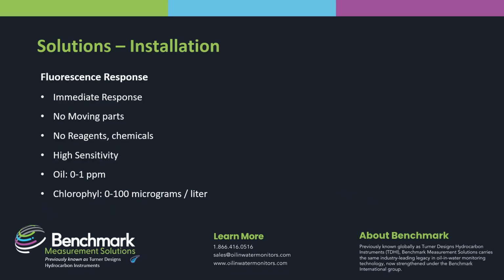Fluorescence is used for this because the measurement has no moving parts, there's no reagents, no chemicals needed. A simple lamp illuminates the process and the presence of either oil, or if the lamp is a different wavelength, algae will be detected by their response. Oil, or hydrocarbons or fuels, depending on how you call them, can be measured significantly below 1 part per million. Most membranes have a warranty stating that oil should not be present higher than 1 part per million in the seawater, so having a range from 0 to 1 ppm is ideal.